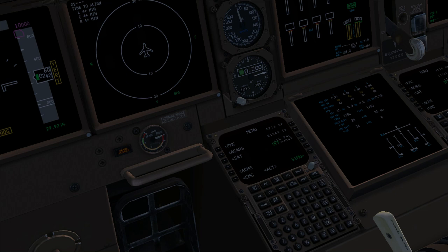First of all, I want to tell you, we are going to take off from runway 17, and we will land back on runway 17. We will just follow a LAVPA 6 Romeo departure, and we will arrive at the LAVPA waypoint, and at this point we will join the standard terminal arrival route of LAVPA 8 Mike. Both of them are RNAV procedures, and we will use an airplane after that to return to the airport.